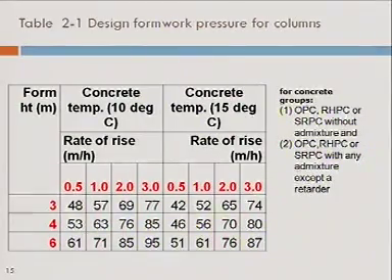So, in order to help the designer, what they have done is they have developed certain tables for different parameters. So, depending on what parameter you are using, you can refer to these tables and you can calculate the lateral pressure depending on your concrete element.